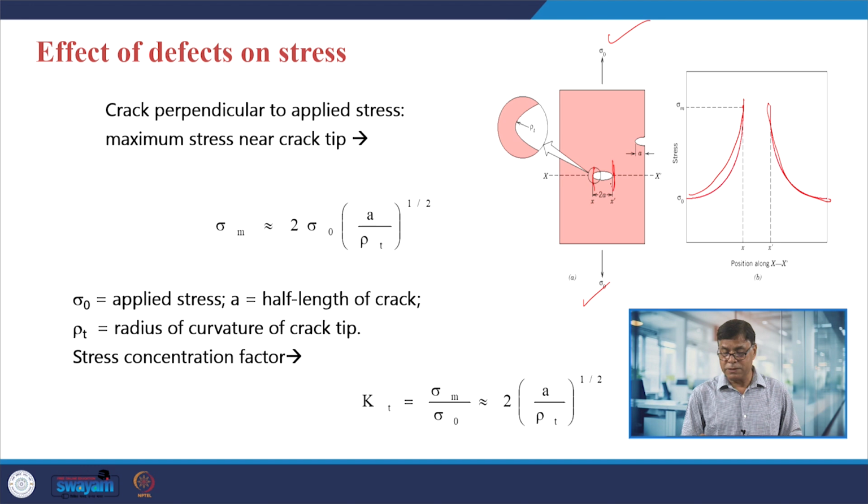The stresses will be maximum in the vicinity of the defect, and if the maximum stress crosses the ultimate strength limit, then in case of low ductility, high hardness and high brittleness materials, the crack will simply propagate, and catastrophic fracture can be observed.